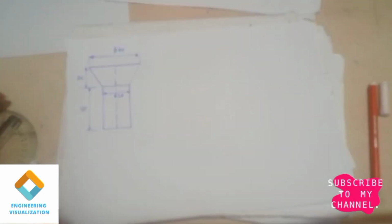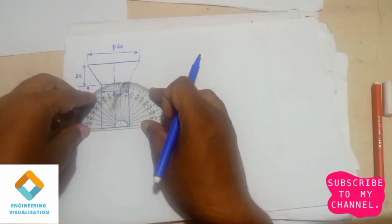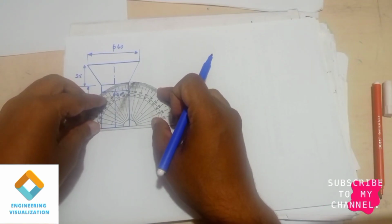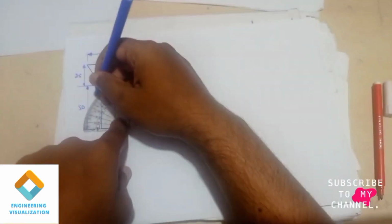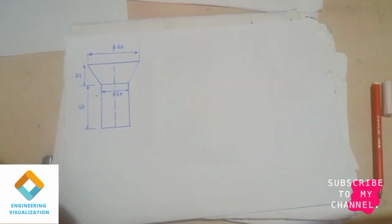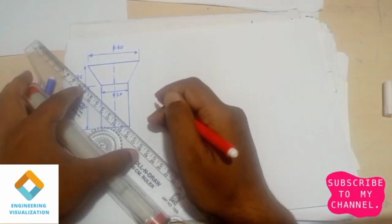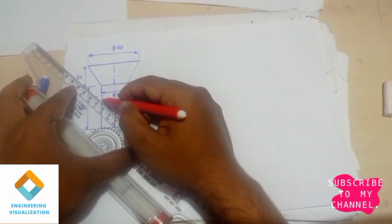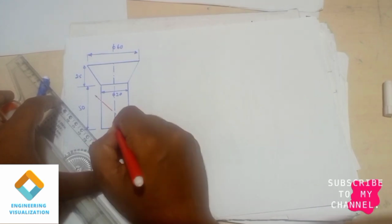So take the protractor. Mark to one of its corner ends. Yes, we should be marking one corner end. So mark an angle of 45 degrees. Okay, now draw a section line, cutting it, to show the section line. I'll be using a different sketch pen. Line dot line. Okay, so it is exactly cutting at an angle of 45 degrees.